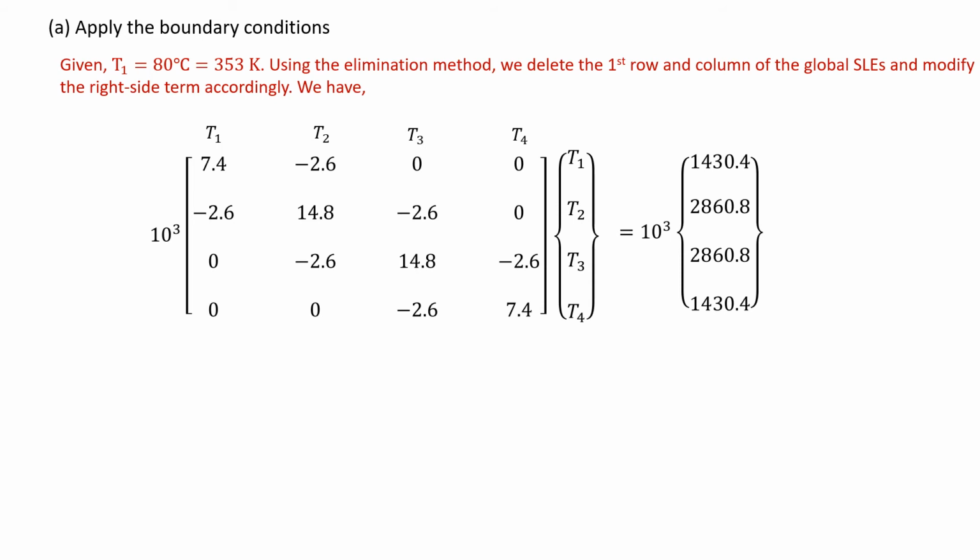In this example, actually, there are two boundary conditions. The first one is the heat flux at the tip of the fin as well as at its side surfaces are 0, as we assume those areas are to be insulated.